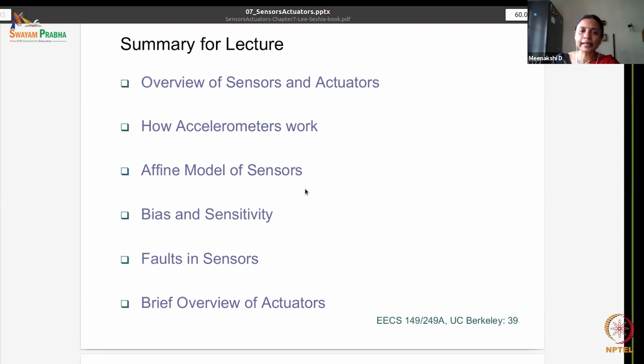While handling interrupts, you have to be careful that interrupts don't take too much time because the main code's functionality still has to run. How much time will it take to switch context? If there is more than one interrupt, do I prioritize one over the other? How do the interrupt service routines interact with the applications in terms of priorities and taking over and passing back the control? How do the interrupt service routines interact amongst themselves? All these are issues that we have to handle.